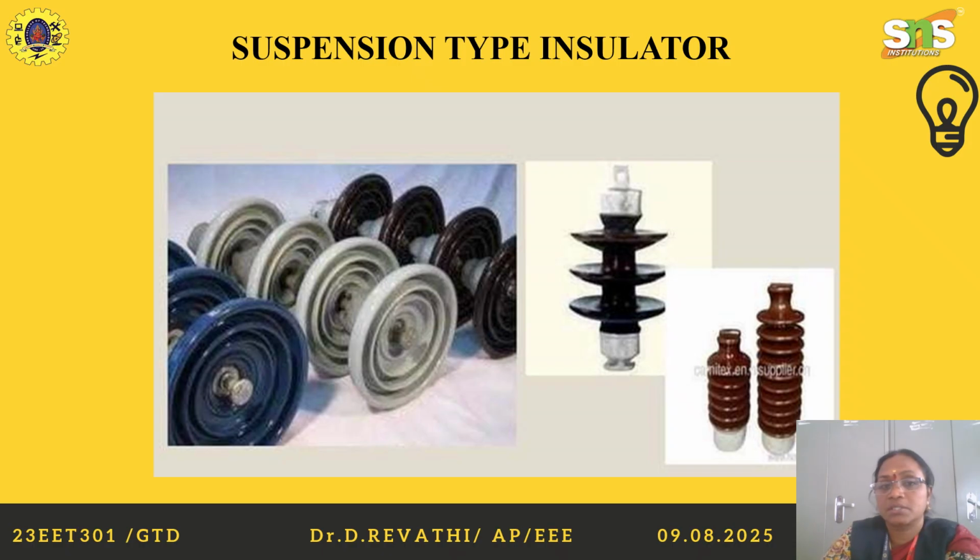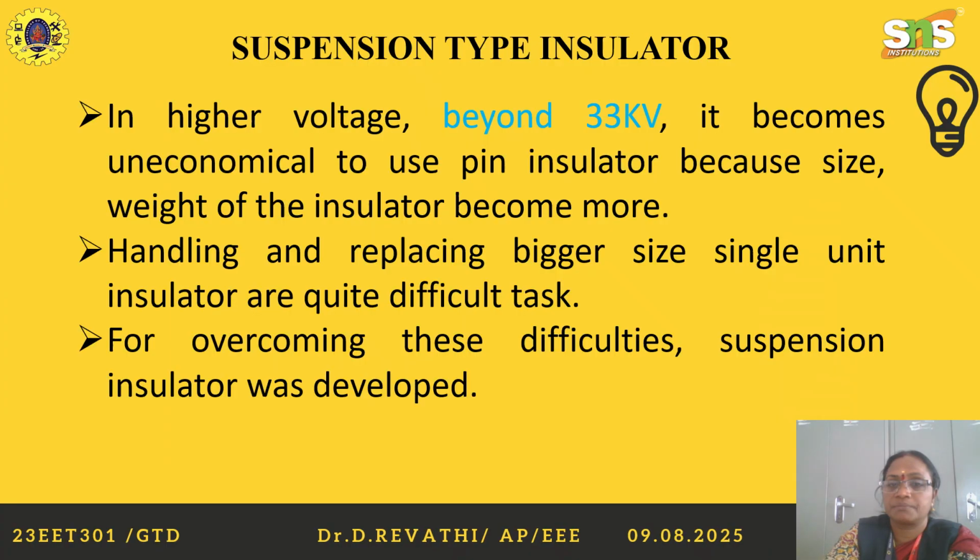Clearly we have discussed it. The suspension type insulator is listed here, see the diagram. Already we said it is a disc type insulator. It seems like a disc, so that's why it's called the disc suspension type. And we use this beyond 33 kV.